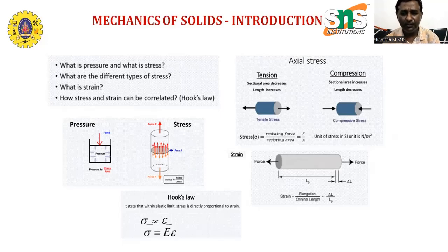The typical value of the Poisson ratio for most materials ranges from 0.3 to 0.5. But for cork it is 0, so there is no change in the lateral dimension relative to the linear. For rubber it is approximately 0.5, exactly 0.4999. For steel it is 0.3. So these Poisson ratio values should be taken care of and kept in mind.